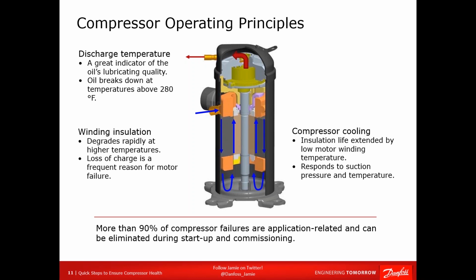You'll notice the blue lines entering into the right middle of the compressor. That's your suction gas coming in. All compressors that have a built-in motor, hermetic, semi-hermetic, this is hermetic, require this returning gas to cool the motor. Either the vast majority or all of it, motor cooling, is provided by the suction gas. So when that suction gas finally reaches the motor outlet after cooling the motor, it has risen in temperature substantially before it enters into the compression area of the compressor.